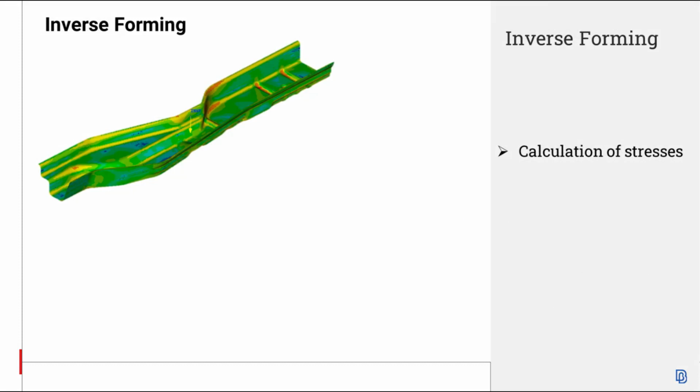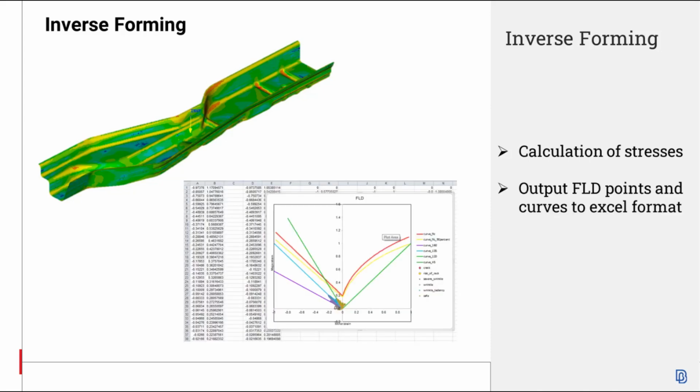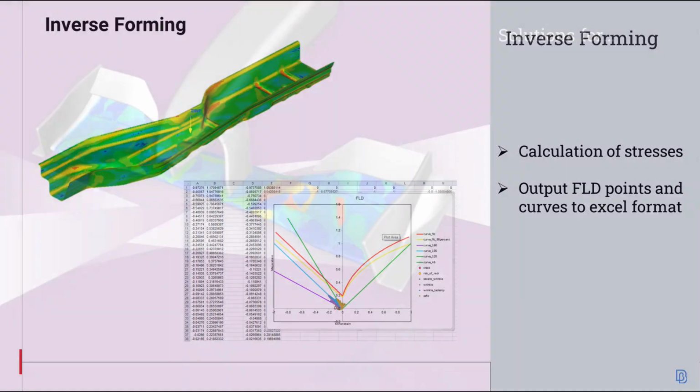Regarding the improvements of the inverse forming tool, the tool is now able to calculate and display stress results from an inverse forming analysis, and furthermore, the users can output all the FLD points and the respective curves in a spreadsheet format.